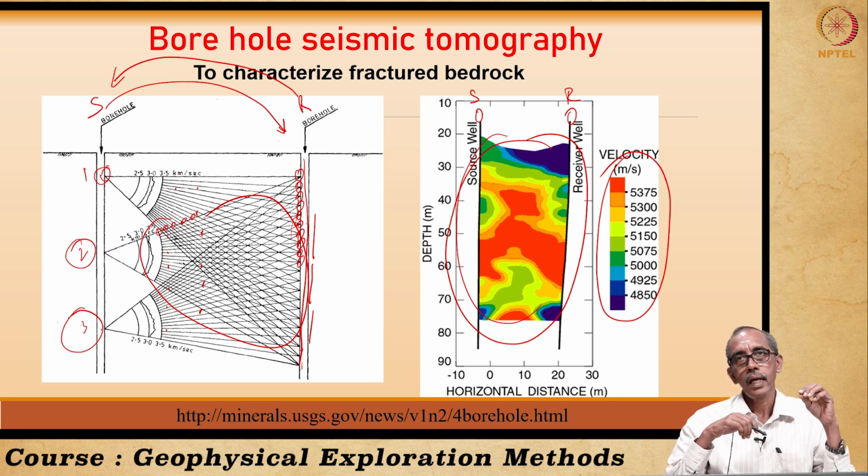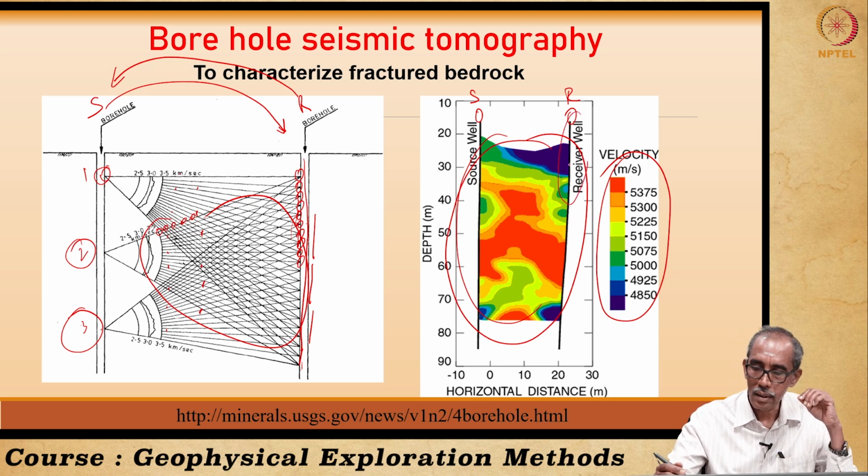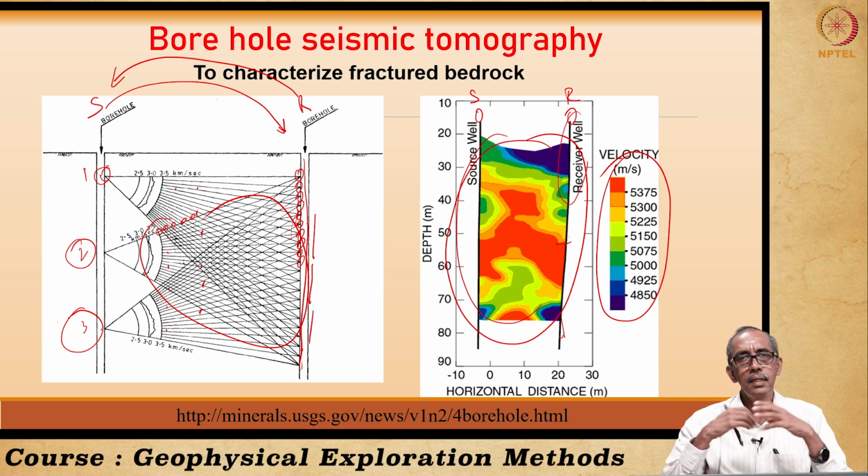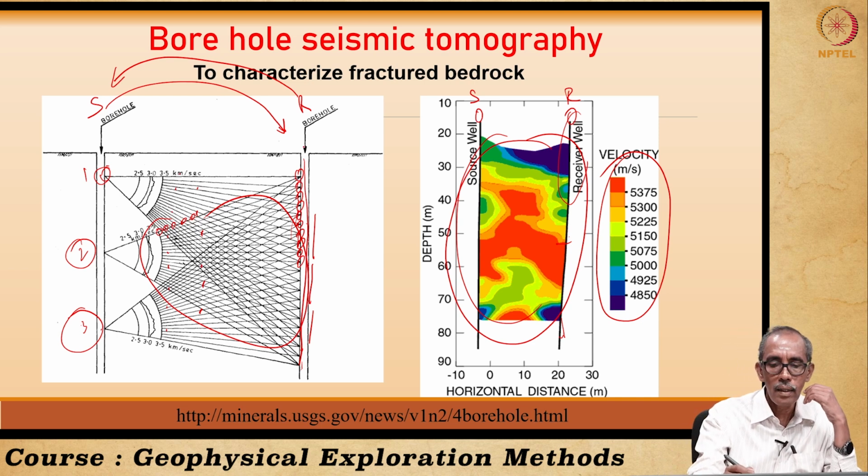And why do we carry out a test on inclination of the borehole? So, here you can have a look at this case. This borehole is slightly inclined, that means it has got some angle here. Though we take all care during the drilling of boreholes, depending upon the site conditions and the driller's ability, sometimes the holes are a little bit inclined, which needs to be considered by us, because we are estimating the velocity between these 2 locations.